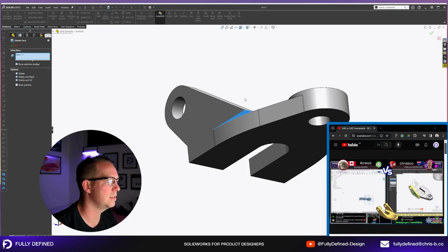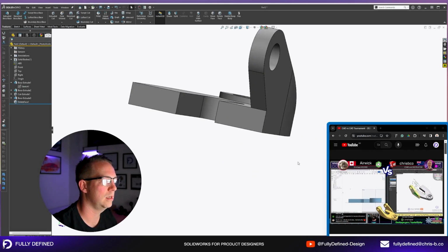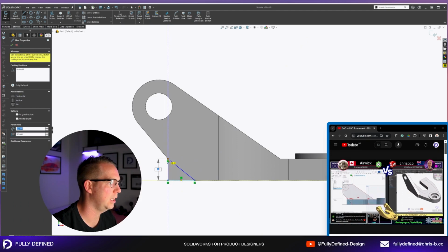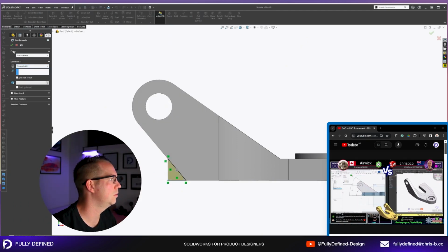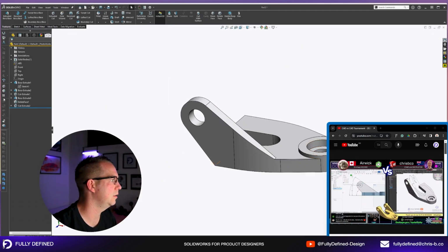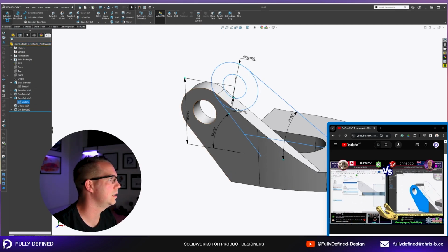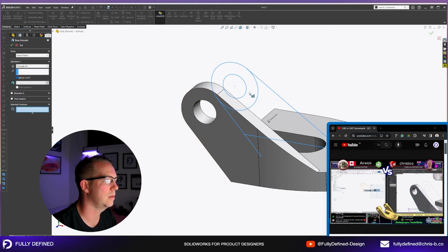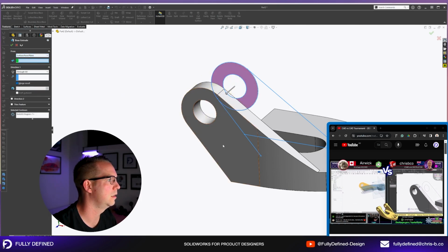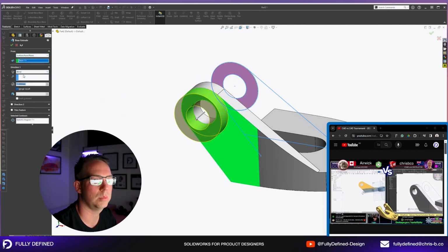Let's see if I can delete face this edge for that corner. And then here, cut that shape to match that through all. And what else am I missing? I'm missing that little circle on the outside. So I didn't do this last time, but this time I could here select that contour, go from this face, blind. That's going out an extra 105 millimeters, I think.